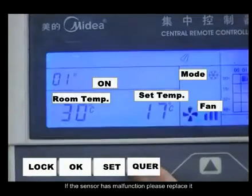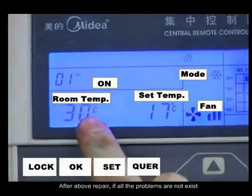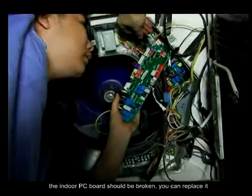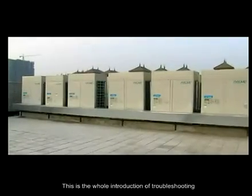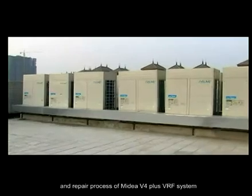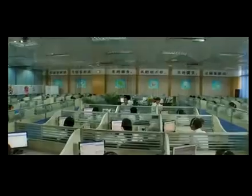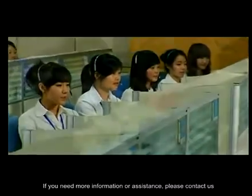You can also query temperature sensor T1 from the indoor central controller to see if it reached the setting temperature. Check if the temperature data collected by the sensor has deviation. If the sensor has malfunctioned, please replace it. After the above repairs, if none of the problems exist, the indoor PC board may be broken, and you can replace it. This is the whole introduction of the troubleshooting and repair process of the Midea V4 Plus VRF system. If you need more information or assistance, please contact us.